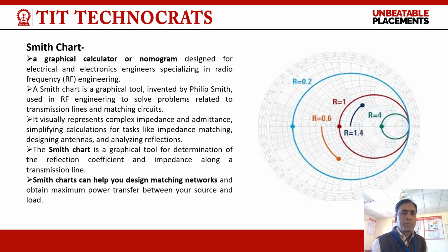It visually represents complex impedance and admittance, simplifying calculations for tasks like impedance matching, designing antennas, and analyzing reflections. The Smith chart is a graphical tool for determination of the reflection coefficient and impedance along a transmission line. The Smith chart can help us design matching networks and obtain maximum power transfer between source and load.